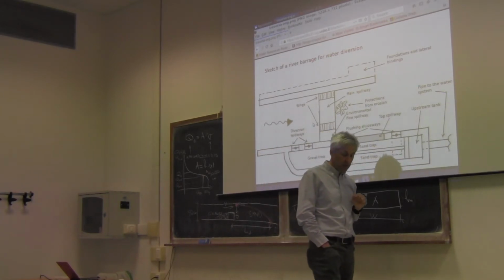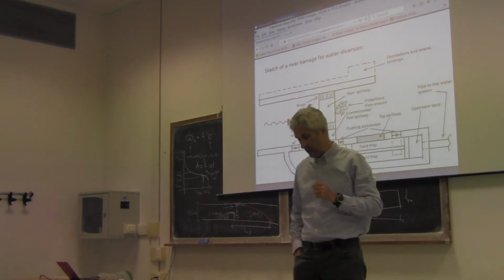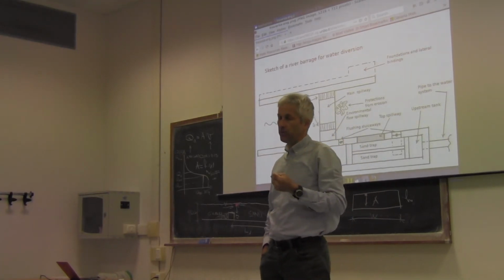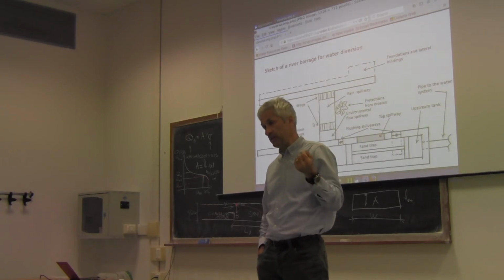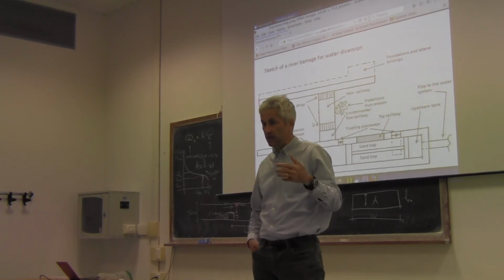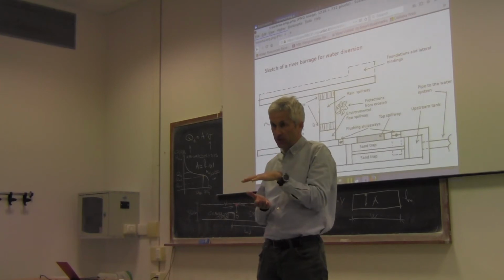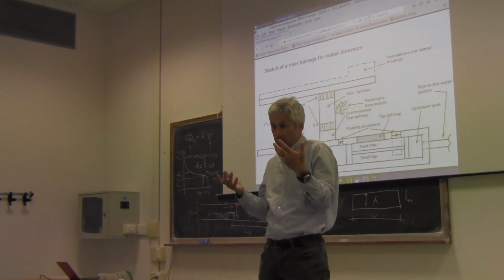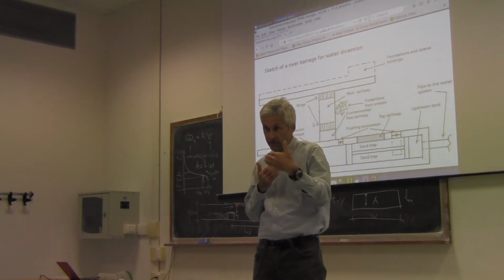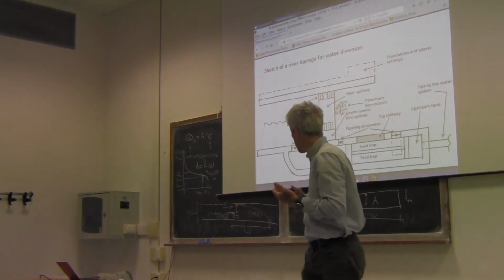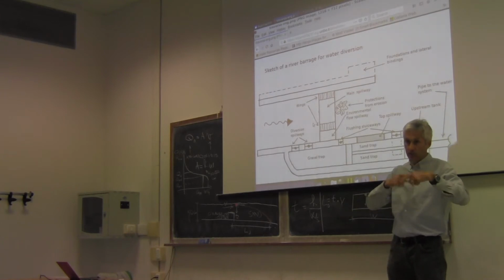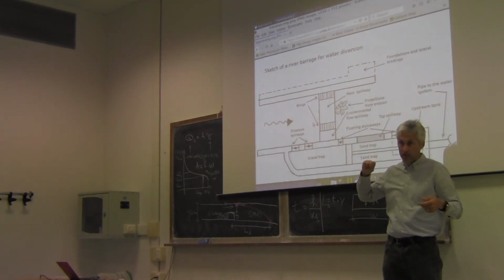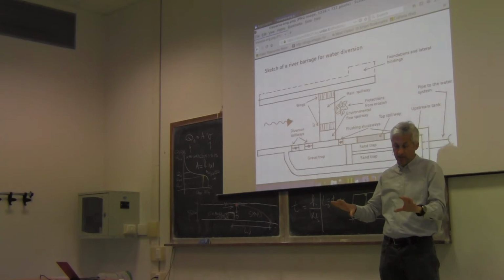Now we are checking the opportunity of making this kind of low-head hydropower plants which have a very limited impact because they can use natural jumps in rivers, and even if you have a natural jump of a couple of meters or even 1 meter, if the river is very large, you can build a structure that allows you to withdraw the water before the jump, route the water through the turbine and release water just downstream of the jump.